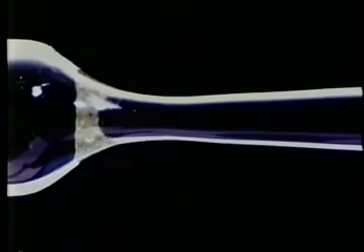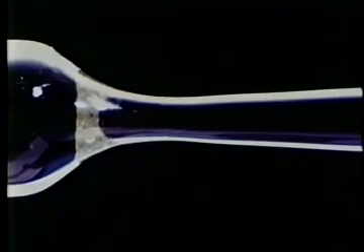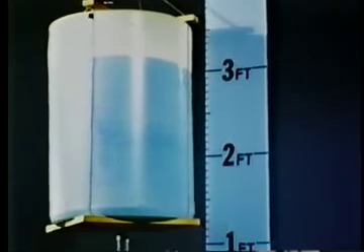During the settling period, some nuclei could rise to the surface and vent if they were very large, and some could decrease in size by diffusion of air into the surrounding water. Consequently, a greater pressure reduction was required to cause cavitation in that sample.